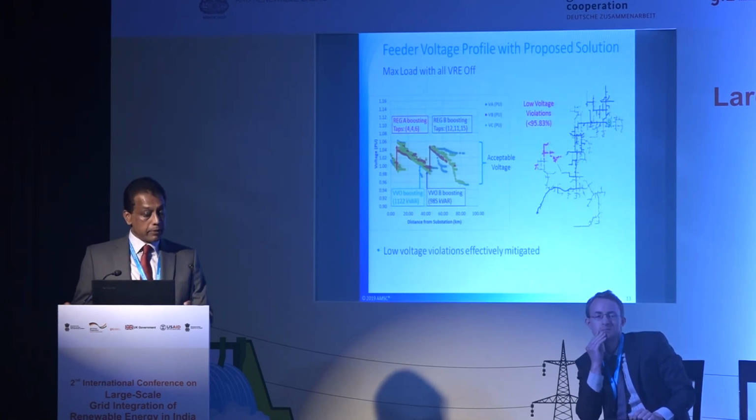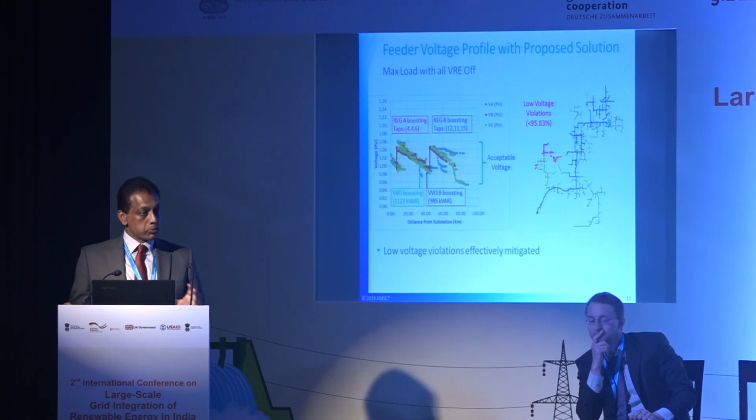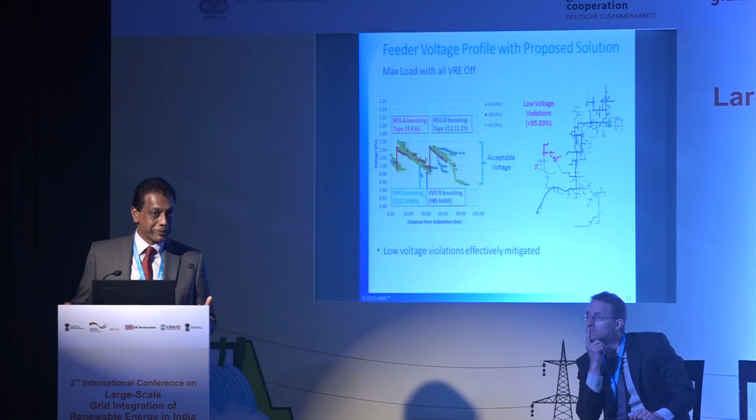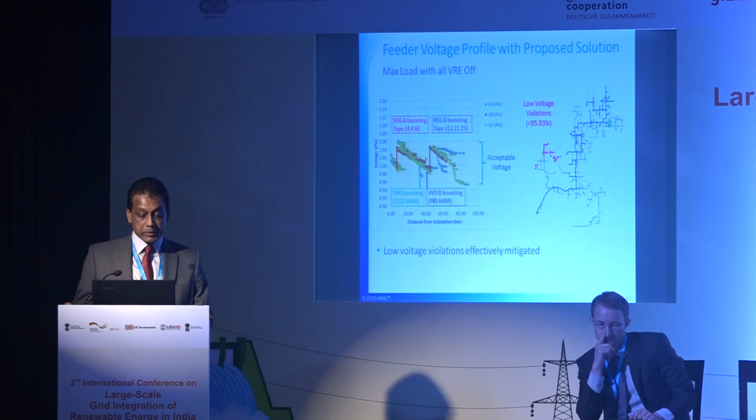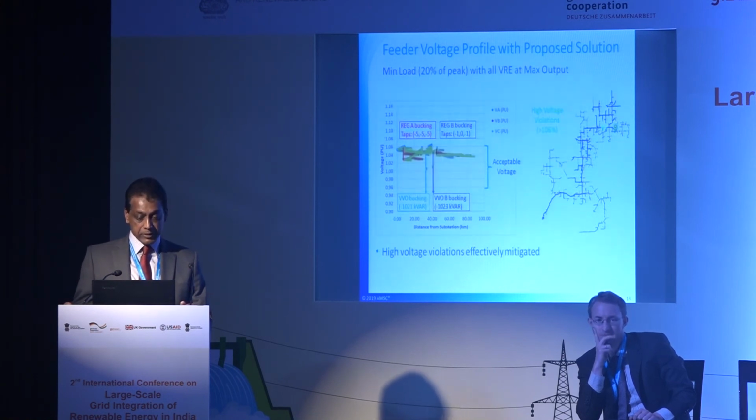It really comes down to how much current you put in, because as a STATCOM, current has a direct effect on the voltage change. So on small distribution feeders, you cannot put 5, 10, 20 megavars of equipment. It has to be in the 500 kVAR to 1 megavar range to be able to manage the voltage out there.